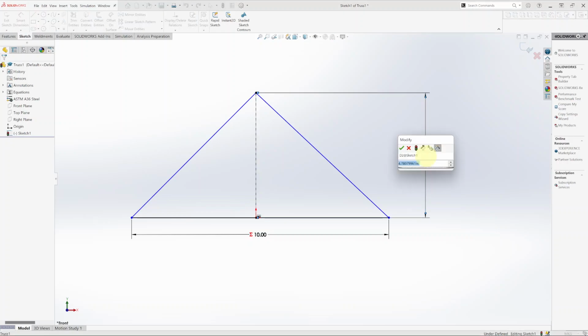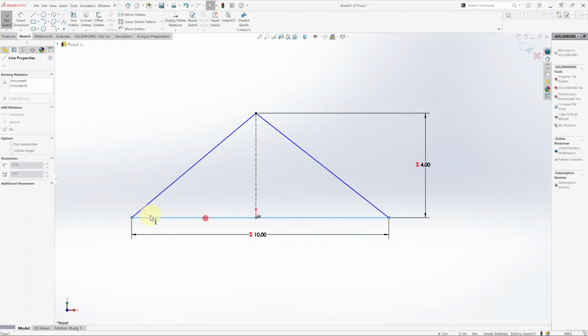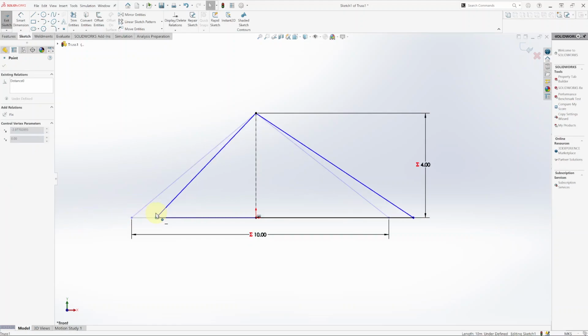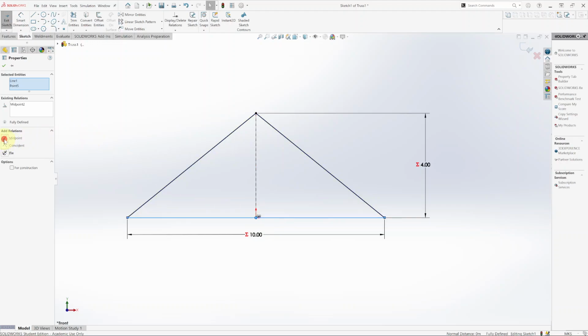And you double click, equal, global variables, and you select the 8 and enter. Here we go. So this is blue. Why is this blue? You want it black, probably because it's not centered. Let's check. Yes, I can move those points. So I will select this line and the origin with control and say that they are midpoint.